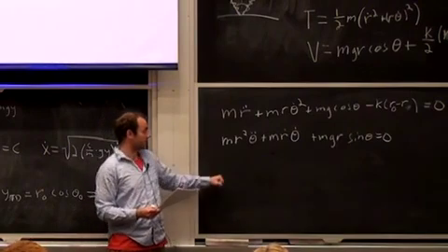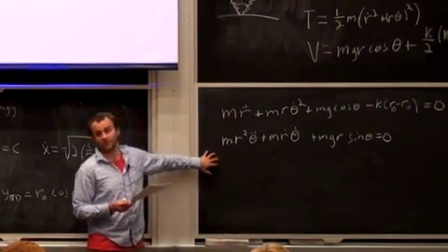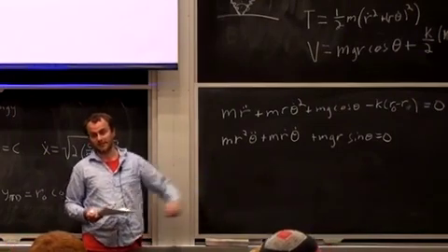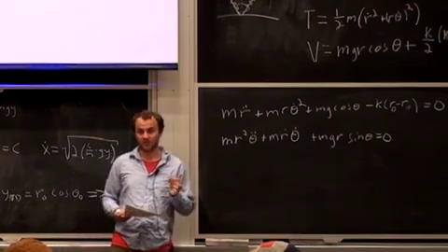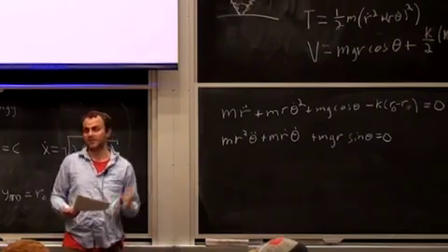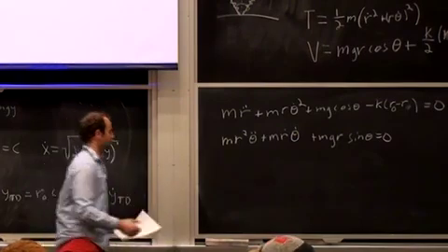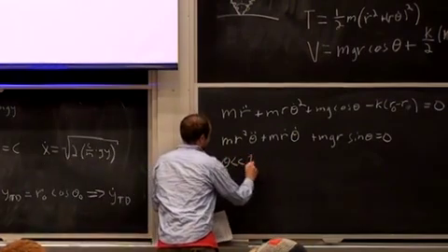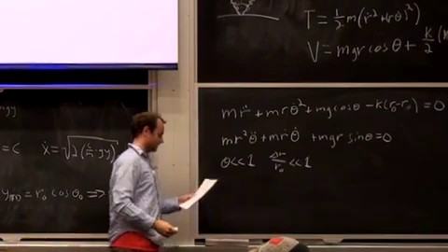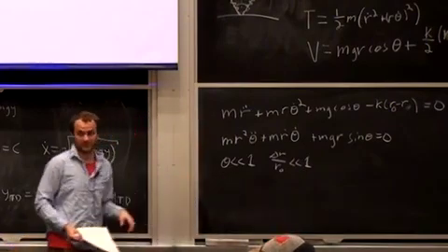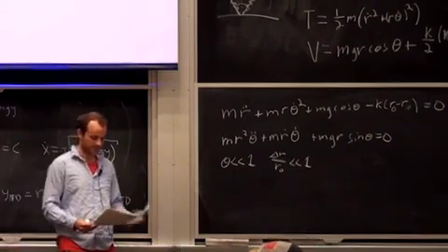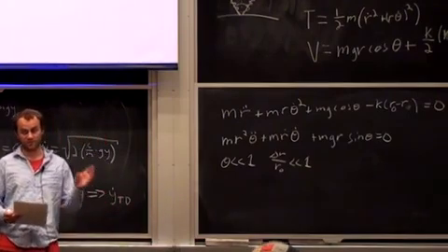And so if you want to get from touchdown to takeoff, you can't get a closed form solution from this. You can simulate pretty easily, obviously, but you don't get the closed form, so you can't get this analytical kind of mapping. But if you use a small angle and small displacement approximation, you can linearize the system, and you can get a closed form solution for this touchdown to takeoff phase. All right? And so that is the assumption that theta is much, much less than 1, and your delta R over R naught is much, much less than 1. And then you can get to a closed form solution. It's kind of ugly. It's not so ugly as to be prohibitive, but I'm not going to write it down. But that lets you actually get a closed form return map.